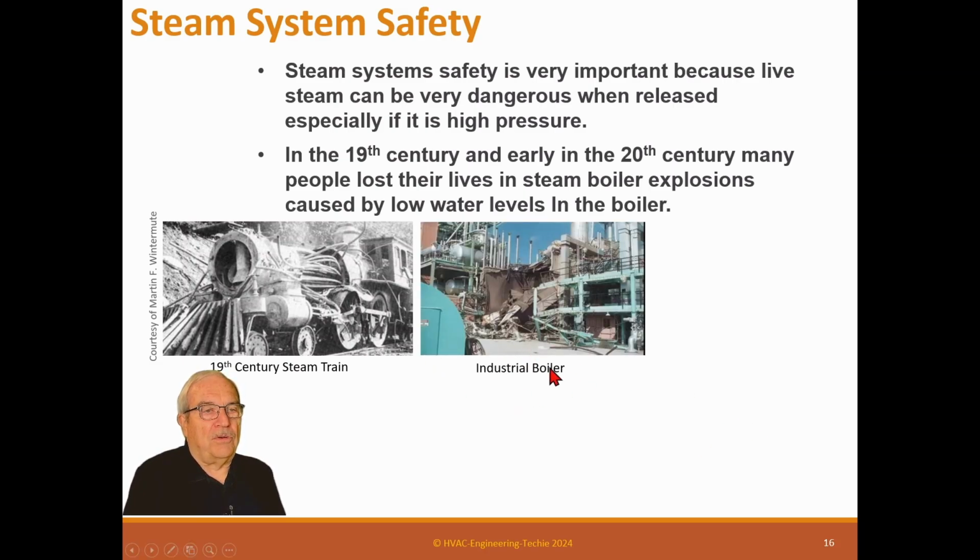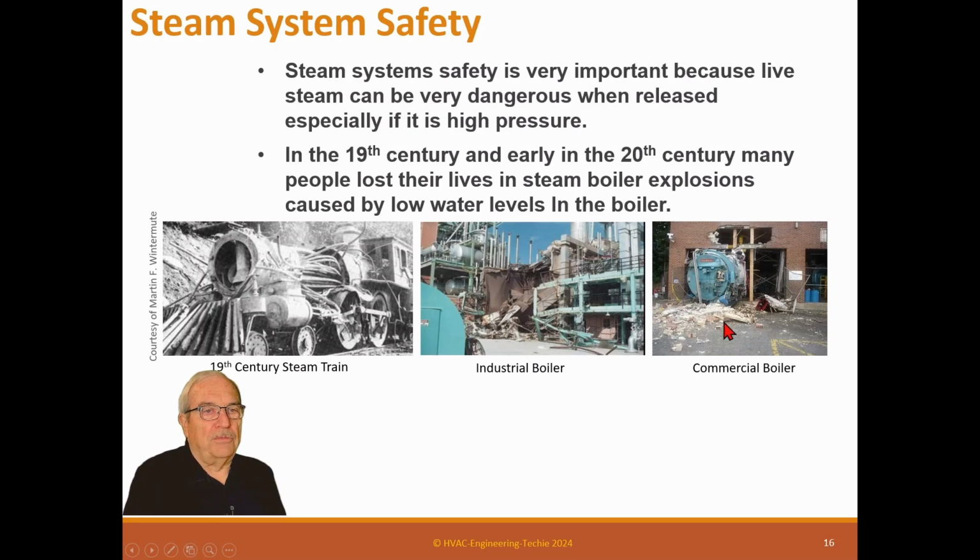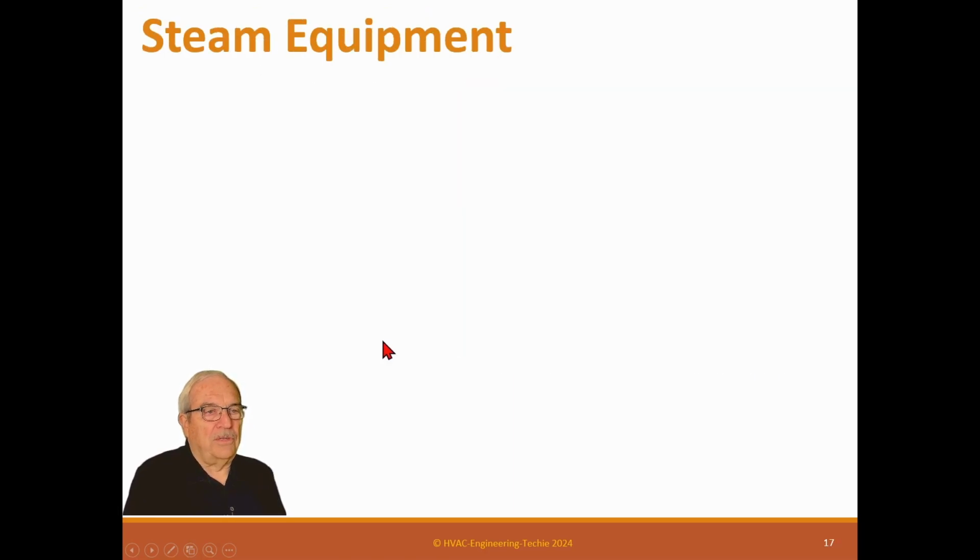This is an industrial boiler that blew up. This is a commercial boiler that blew up and knocked the side of the building out. A whole bunch of things can happen if you let that happen. So remember, make sure the water control is correct. It's really, really important.